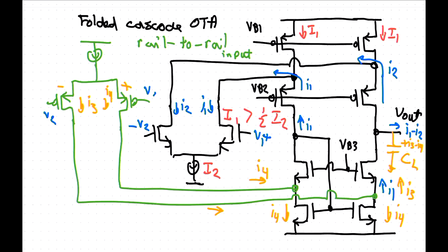What is loading this transistor is a diode-connected transistor, and you have the same problem. You can't reach a negative power supply. It's the same condition. But this is why it's so nice that you can go in there. There's nothing wrong with going in at this point of the current mirror, and it's a good place to go into the current mirror.